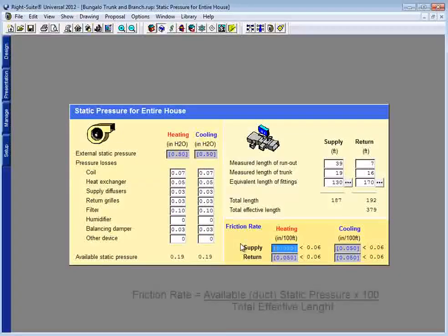As I look at my static pressure page, I see that there are basically two halves to this equation. There's the total effective length, which is the layout or geometry of the duct system itself. And a lot of time that's going to be defined by the actual building, where you can actually fit a duct. If there are options of using straighter runs or fewer turns, you should most definitely take them. But once you've exhausted those options, your next best bet to lower this number is to use the best fittings that you can afford to use for this job.